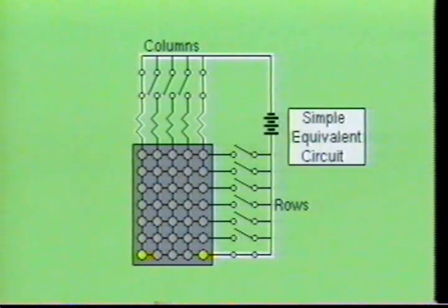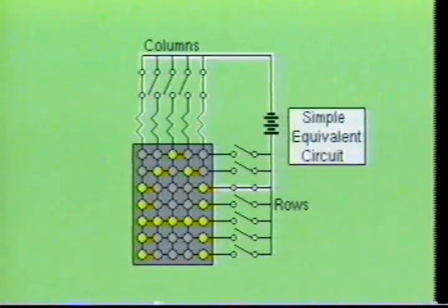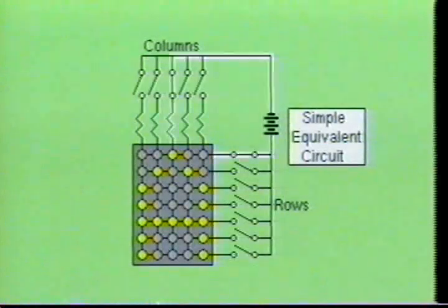The character generator next scans row 7. As row 7 is being scanned, a high is placed at inputs C1 and C5, which results in these two diodes being turned on. During this example, the rows were illuminated one at a time, since this is the system by which the character generator functions. However, the scan rate is so fast that all the LEDs in the unit appear to be activated at the same time.